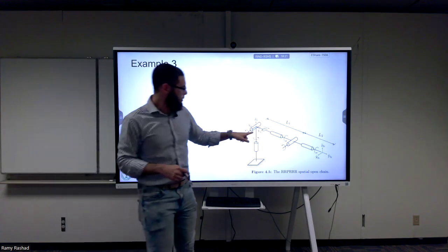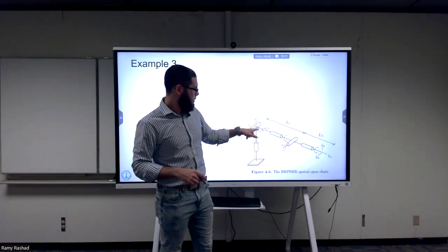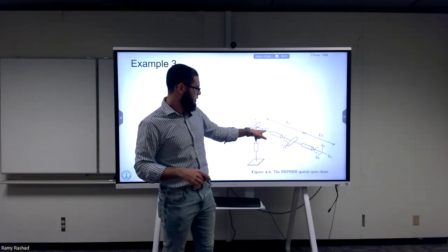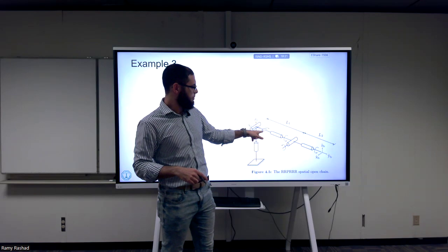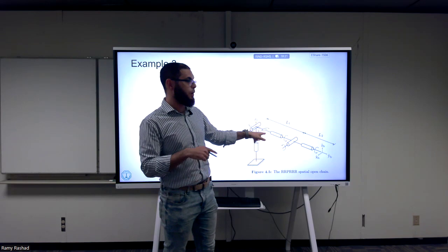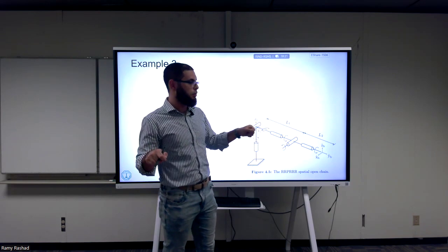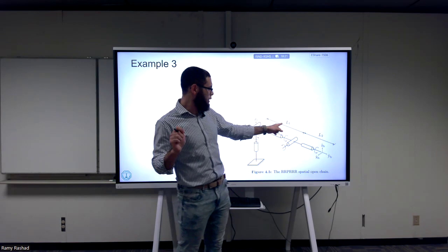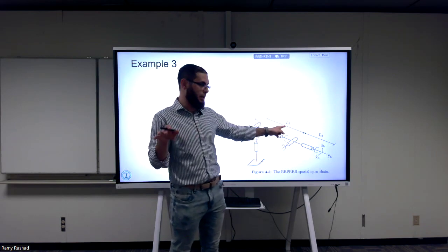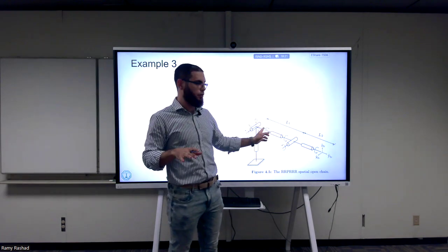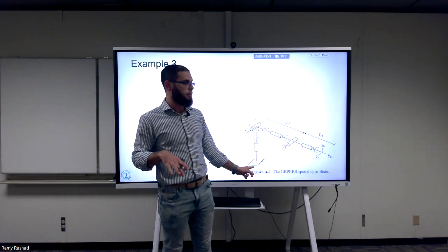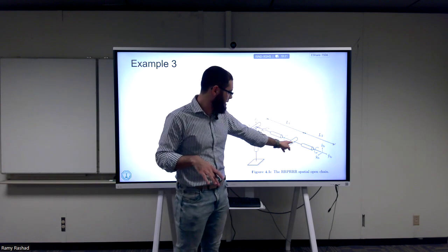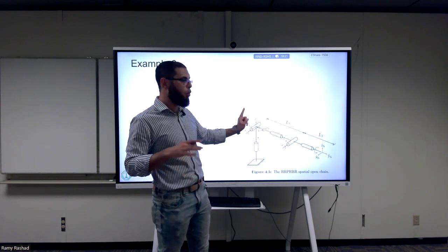Let's see. Let's assume at this end we have a prismatic joint, between B and there. This is a prismatic joint. If it's moving there, do we have a fixed length between the consecutive frames of the prismatic joints? When the joints extend, no. So L1 will change when it starts to extend. But we don't care, right? Because we do everything in the home configuration. You get the transformation from this frame with respect to that frame only in the home configuration.